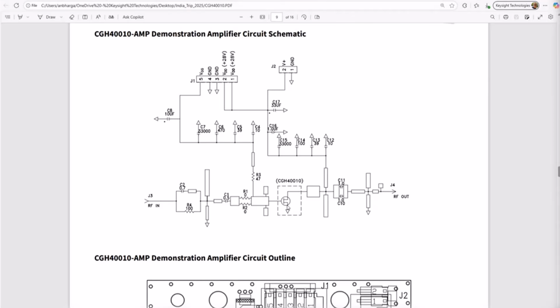That means they have a high inductive content, or reactive content. So you would like to make sure that it sees the minimal amount of parasitics, because slight mismatch here, there, your device can go into oscillation, and instead of making a nice PA, you will end up making a nice oscillator. All right. So make sure you have enough bypass, you take care of all these parasitics and so on.